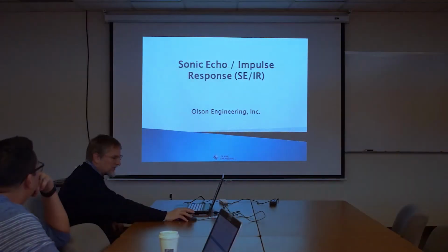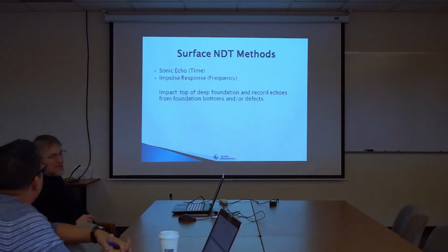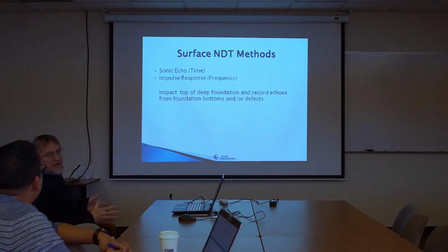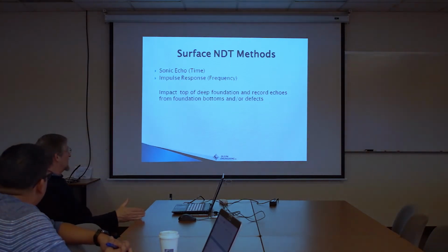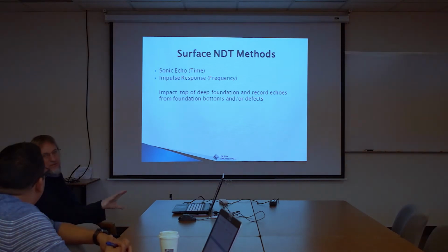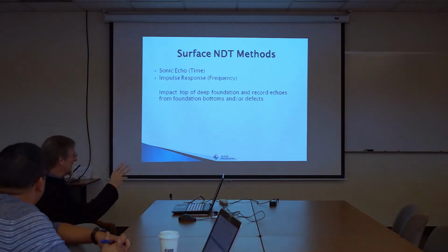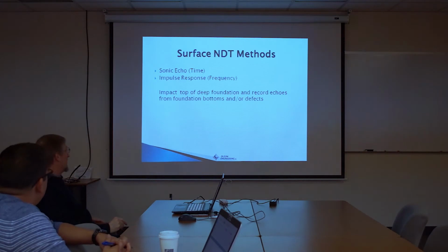So essentially, we're going to start with the basic SEIR slides. It's a surface method, done from the top surface. Sonic echo is time domain analysis, which is what we're doing here. Impulse response does the same, using similar data with an instrumented hammer, and does a frequency domain analysis. So we'll show that quick, but we won't talk about it too much.